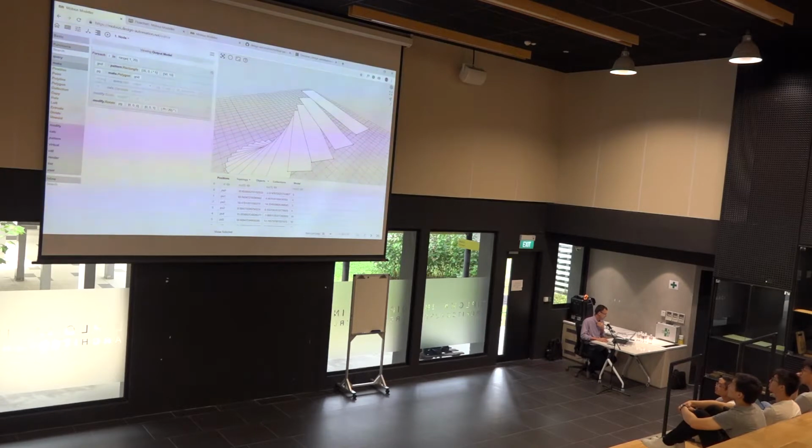So this query here is saying, I just made a polygon in this line, and in this line I'm saying query.get edges of this polygon. And this one is a condition, but we set it to null, there's no conditions. So this one returns the 4 edges. So we can print this.